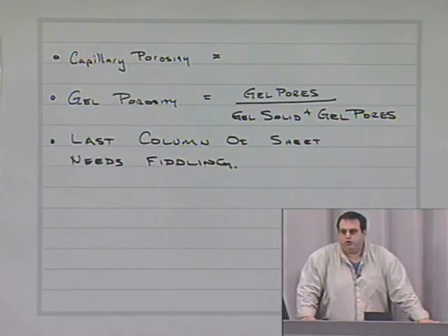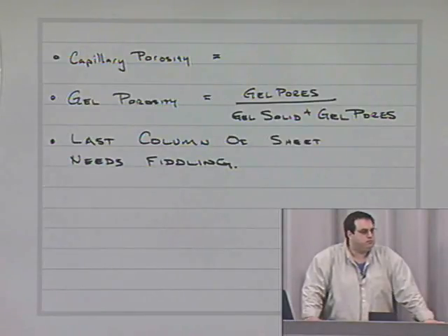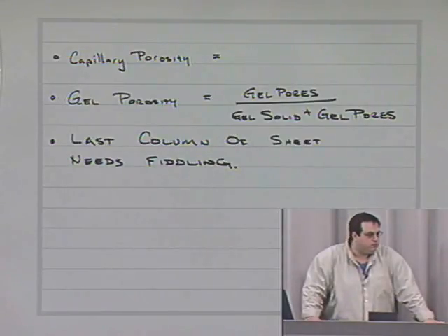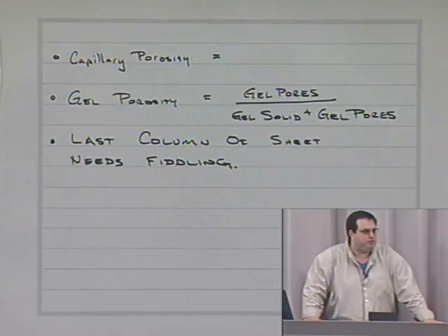Okay. Other questions as it relates to homework? What do we mean by empty pores? Does it include chemical shrinkage or it doesn't? Empty pores will typically include chemical shrinkage, capillary pores, and even gel pores if we dry it out. So the easiest way to answer that question would be to talk about the 3 types of pores, and then you could calculate the total volume. Other questions as it relates to the homework?